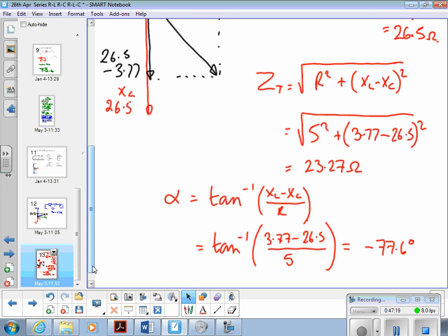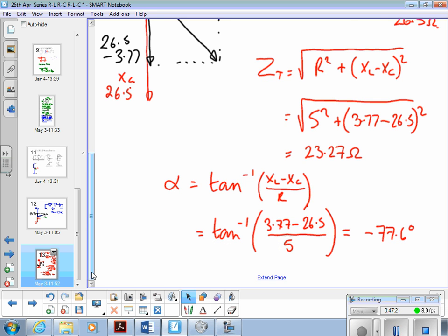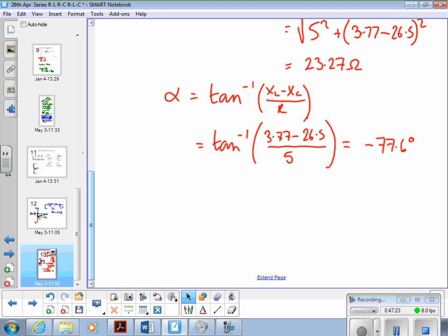Alright. You don't generally find, particularly in power circuits, where the capacitive reactance is the higher. It's usually inductive loads like motors and transformers that make a quite high inductive reactance that needs correcting with capacitance.